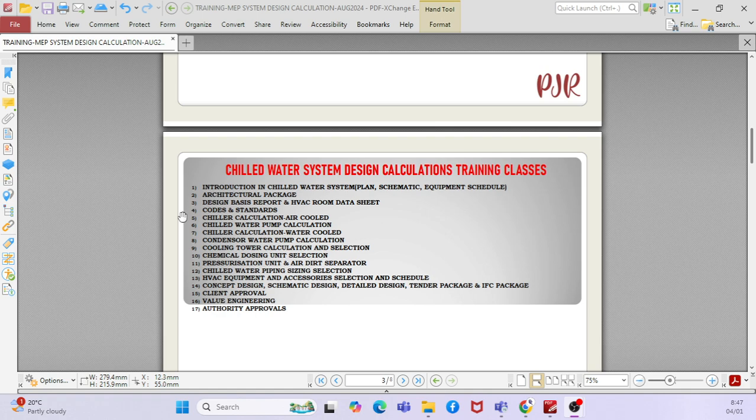Pipe sizing is normally based on the manufacturer, because this is based on gases, right? It's not water. This is based on gas, and there is a length or distance restriction. That can be done by the software, but we have to prepare the schedule basically. Based on the schedule, they can provide you the complete tree diagram, like when you go to the VRF, one outdoor unit consists of how many indoor units. That tree diagram they can provide you.